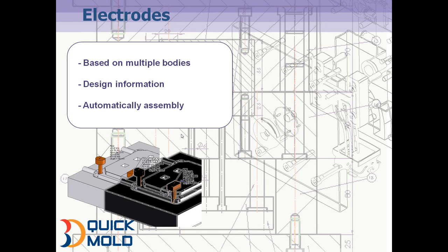So at the end you can see this is not just a mold design. We have an electrode solution for electrodes also. Finally, to manufacture any core and cavity, we need electrodes for complex areas. So here, by using the electrode wizard, we can create electrode bodies quickly and easily. It also helps us to create a holder design.